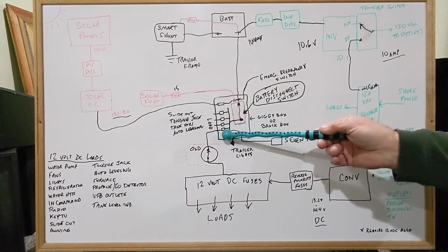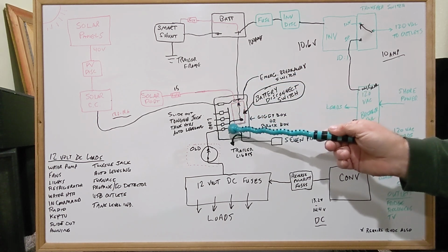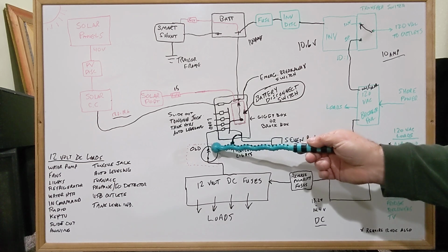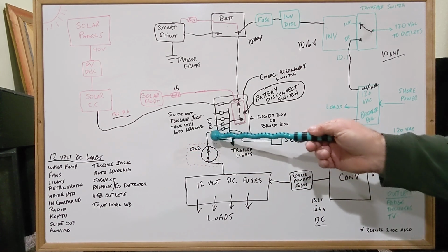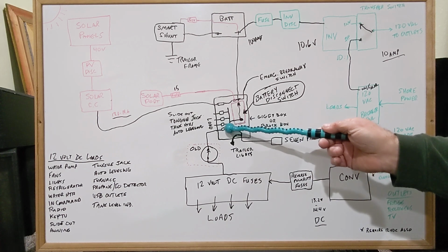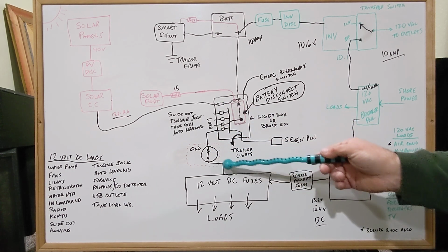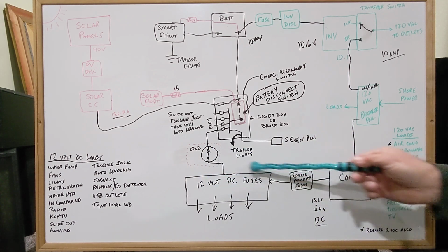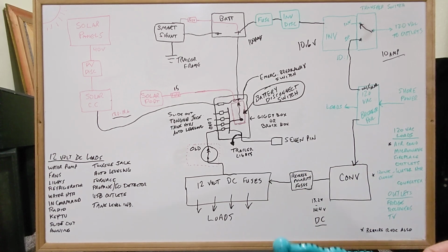One of those breakers is a 50 amp breaker, and the battery fed down through that breaker, and it had the old battery disconnect switch. That battery disconnect switch was in the line going from the breaker on the tongue to your DC fuse panel, so it only disconnected this. It didn't disconnect all this other stuff up here that we're going to talk about in a minute.